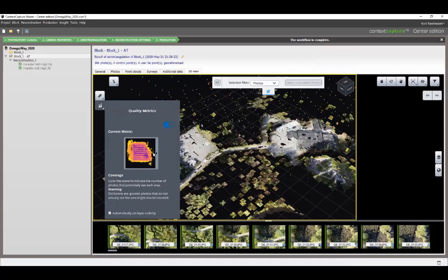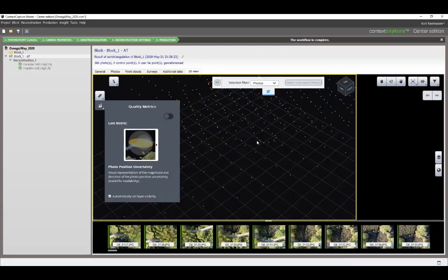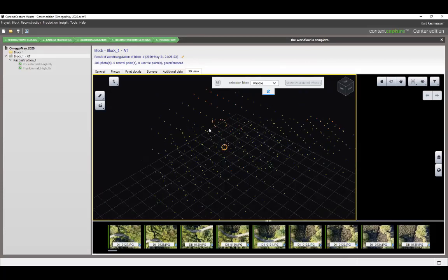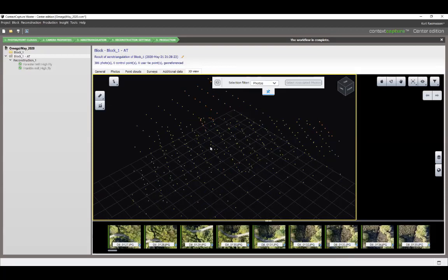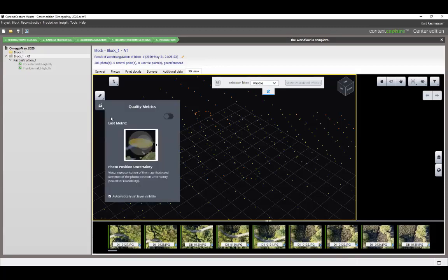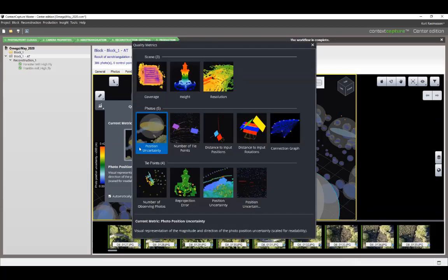We also look at position uncertainty. So we could see over here, I know it was uncertain here because you'll see how this area here, when I was flying the drone, there's two areas here. One has this loop here and one has this loop here. My drone actually lost signal at that point. So I know it lost connection. Those were thrown out, these weren't, but they weren't very good photos, and it jumps out to me when I look at the uncertainties that are over here because it was windy, it started drifting, and there's uncertainties there.